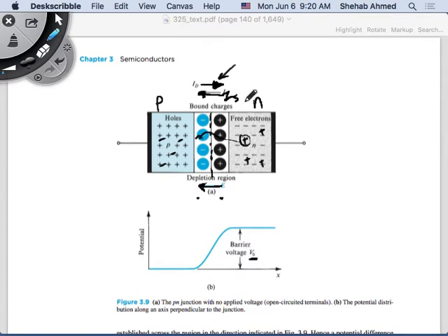Yes, sir. Last time we said like a capacitor, right? It's acting like a capacitor. But this goes back and forth, right? No, it doesn't go back. It only goes from one direction to another. It's an open circuit now. Yeah, we're open circuit. Diffusion current will always go this way, and drift current will always go this way. And in open circuit, they're equal to each other.